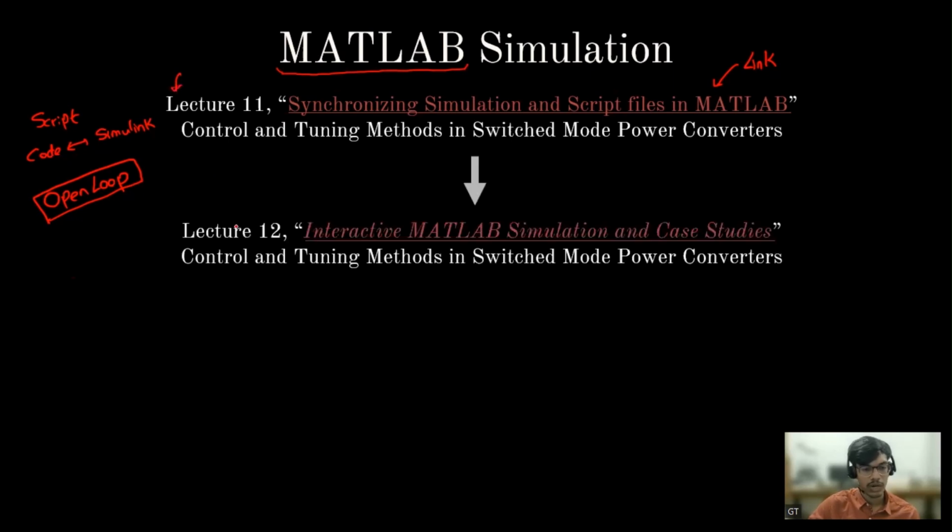After this lecture, you can go through lecture 12 of the same course, and again the link is embedded here. You can directly click this, and it will take you to that YouTube video. This is an extension of this. Sir has considered analog voltage mode control, I guess. Until this point, by looking at these videos only, you can make the MATLAB model of analog voltage mode control. After that, by making slight changes, by replacing the ramp with the inductor current, you can make peak or analog current mode control. Until this point, it would be easy for you.